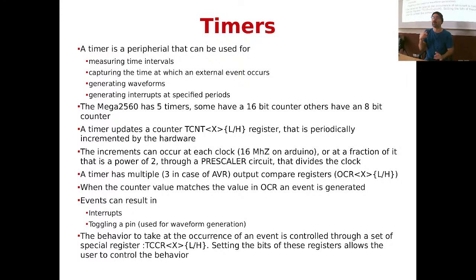So if I generate a signal that is high 75% of the time and 0 25% of the time, and if I integrate it over time, then I get a pseudo-continuous signal that is at 75% of the value, so to say. So the game is that you put a low-pass filter at the exit of this PWM, and the low-pass filter will return you more or less the average value that you read in this square wave over time.